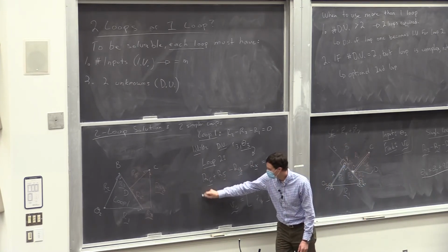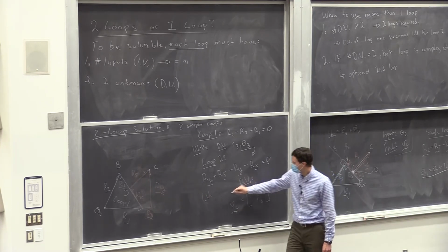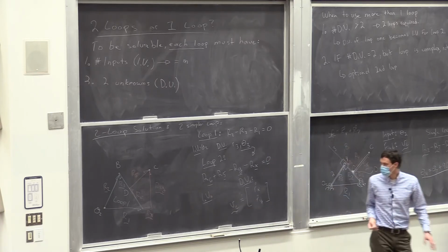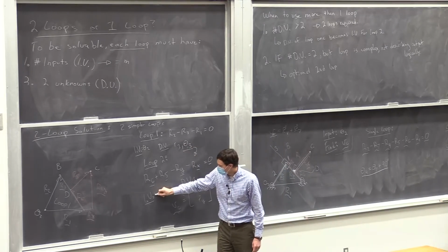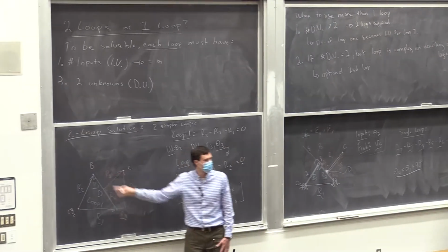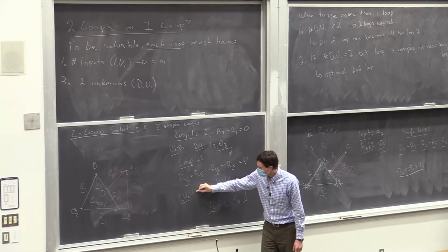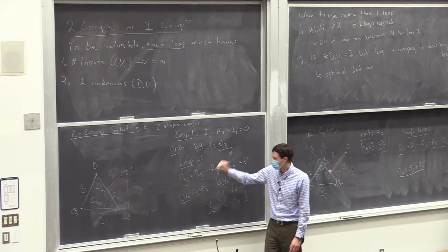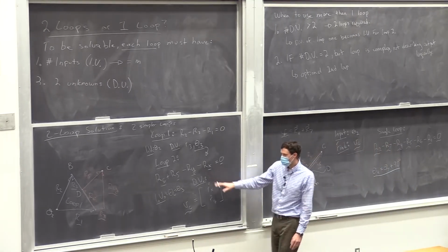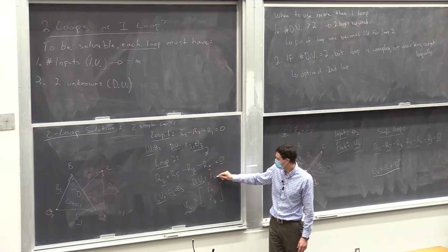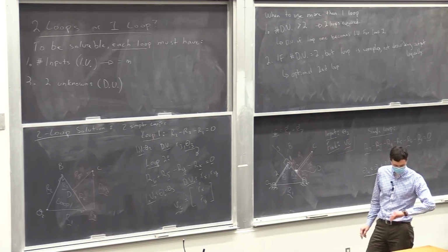Okay, unknowns and knowns, independent variables and dependent variables. Our input to the second loop is going to be the output from the first loop. That's theta 3. So our input, theta 3, is the same as theta 6. Right? I put that along link 3, same on purpose. So we can say theta 6 is the same as theta 3. So that's our input to the second loop, output from the first loop. And unknowns, of course, are going to be this output, Rx and Ry. And everything else is going to be constants for this one.